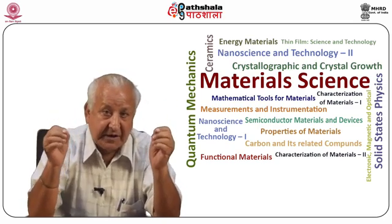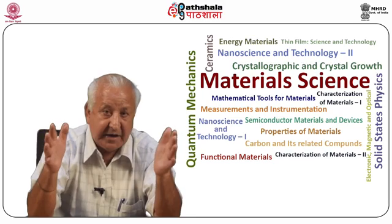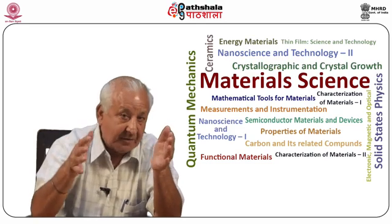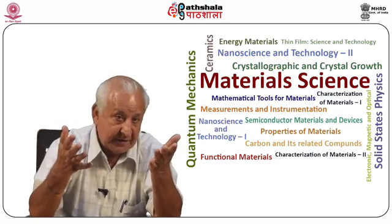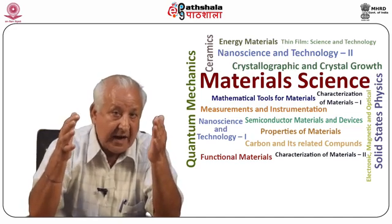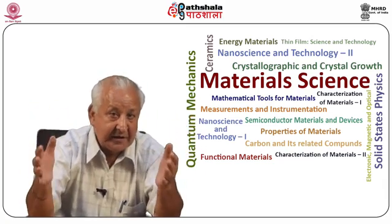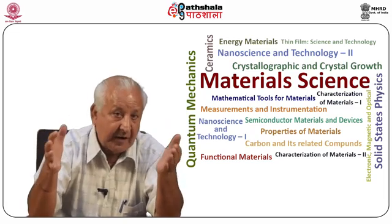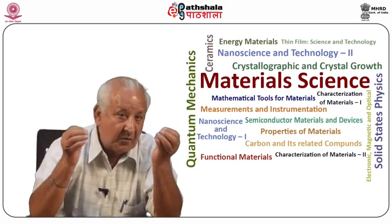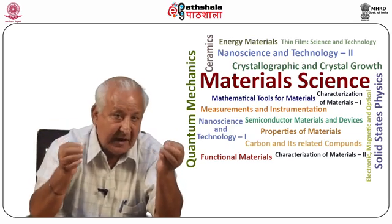The furnace used here consists of two halves, the lower half and the upper half. The temperature maintained at the lower half is just below the melting point of fluorite, and the temperature of the upper half is above the melting point of fluorite. The crucible is made of platinum and has a pointed lower end as shown in the diagram. The crucible is filled with high quality natural fluorite or purified powder if required, to which desired impurities may also be added. A platinum wire hangs the crucible in the upper furnace until the contents are completely melted.